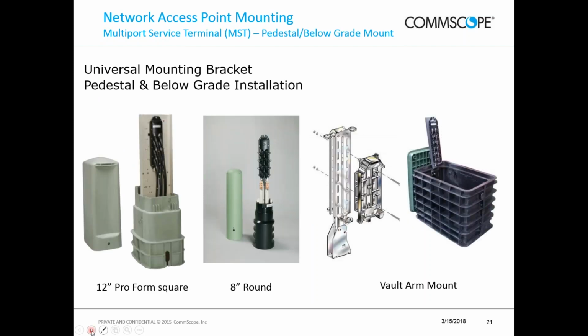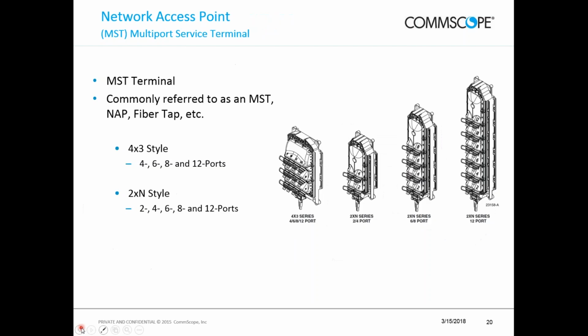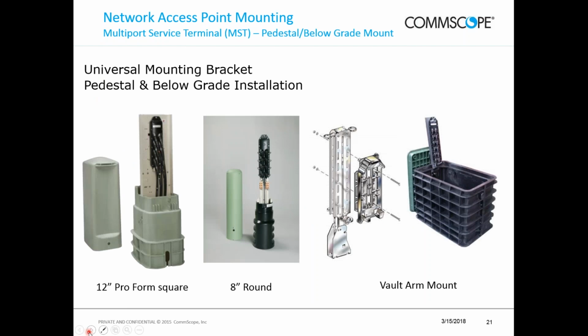Okay. So I guess bottom line, if I jump back to this one, depending on what your company decides to use, it probably most commonly will look like this, but it also may be more of a box-like device with the drop cables just coming out the bottom, and you won't have any hardened connectors on the front. The drop cable will simply be a fusion splice inside this device that's going to fit up on the strand or in a pedestal.